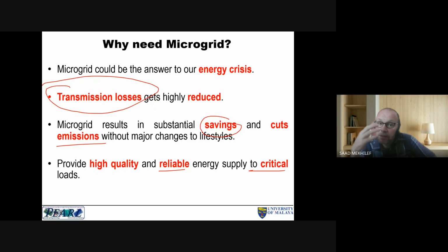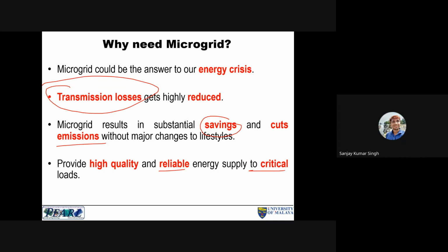And even in the battery, they will have supercapacitors, battery, and diesel generator. Any idea why they have this kind of redundancy? Battery too, because battery is the one which we can rely on when there is a power off. The battery is the most reliable source, so it will immediately take the power supply wherever we require the critical loads. But it has cost, and because we cannot have a very big battery, it will have cost and other complications.